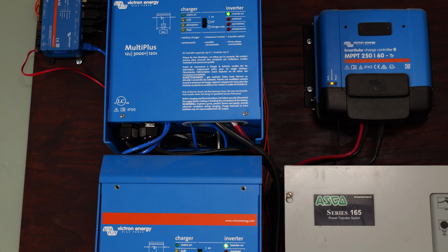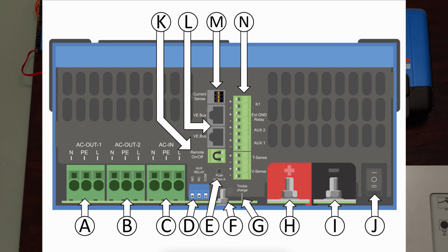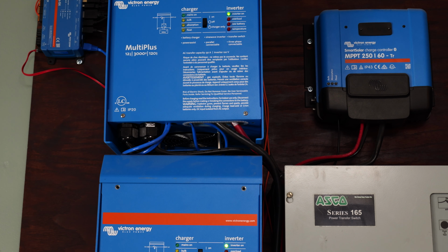The first thing to try when diagnosing this is to disconnect the ground wire that's running out to your generator. Of course, this is not the safe thing to do long term, but as a troubleshooting or diagnostic tool, it's usually the first thing I recommend. And here what you're really looking for is any change in behavior to help point you in the direction of where the trouble is.